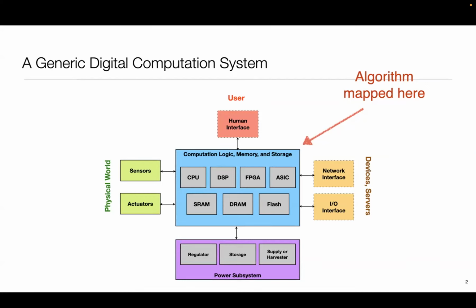There are better ways of doing it now, but that's a century-old way of doing that. And we also discretize it in value. Because we are dealing with real numbers, and of course, we have to represent them in a finite number of bits, some finite sized entity. So if the incoming signal is air pressure, we can discretize it into bins, let's say divide it into 8 bins, 3 bits. That's my digital value.